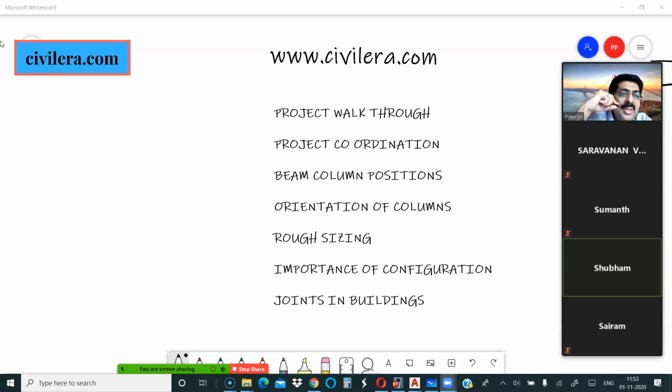Because anyway, you have a slab there, so a concealed beam is nothing but a slab. The only difference is that you are running some top and bottom reinforcement through and through. In slabs, generally your slab rebars are not through and through. Your top bars especially are cut, and your bottom bars are also cut. Your top bars are only near the supports. So the only thing that I am asking you to do is to run your top reinforcement through. Bottom reinforcement anyway you have more length, only that towards the end it is cut. So you are only losing a couple of bars, and by tying it you are getting a better performance. So there is nothing that you should be worried about in providing that.